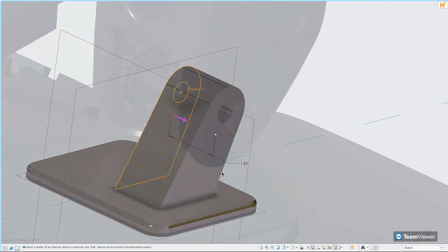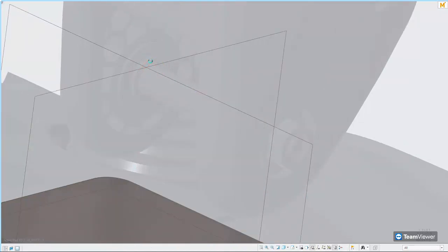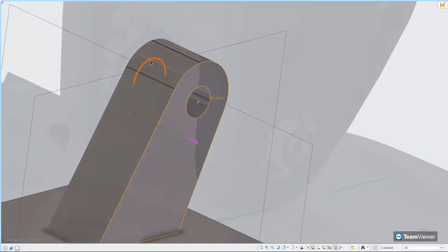Now back to the 3D level, some of the more improved workflows behind there is the ability for me to create my extrudes, but work in different ways. So here I can use my traditional drag handles to a particular reference. And something new within Creo 4 is the ability to offset your extrude in 2 directions at the same time.